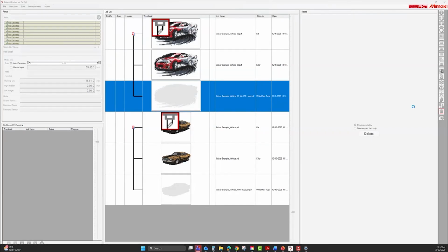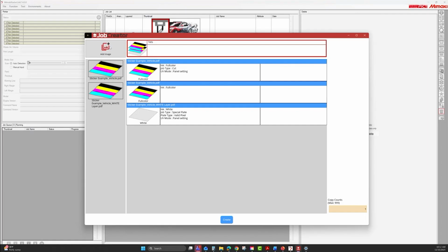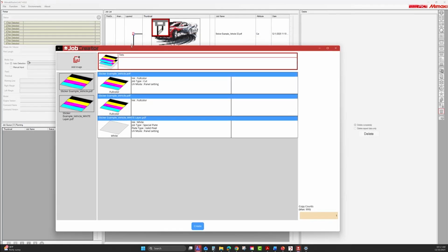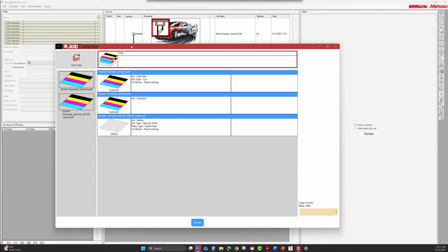It will remember or recognize the crop marks that you used before, but it will not remember ID cut barcodes. So if you made your crop marks inside RasterLink, it will load those back again, but you will have to designate that it's using ID cut separately. There will be a video coming out later explaining how that process will work.